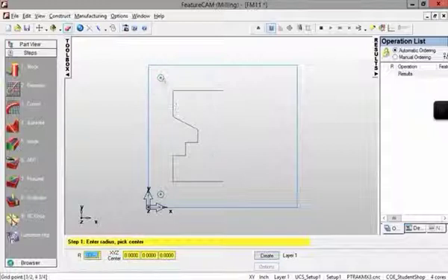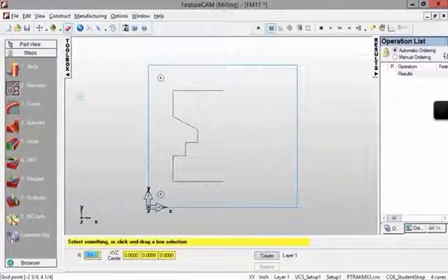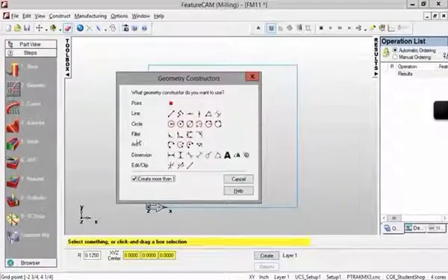Do the same thing for the next dots. So the circles, or the holes, are already here. And then, as we mentioned, we want to do some round-off for this sharp corner. Round-off is still under the geometry button, and actually in the fillet options.